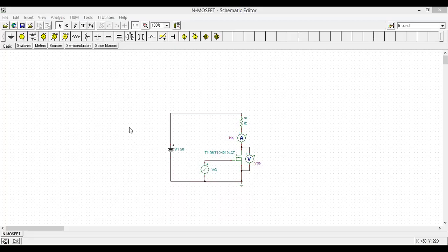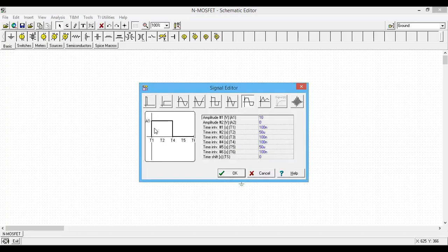All right. So this is the previous table. We had the continuous response and power losses. Now this is a dynamic response. So this is your gate drive signal. I have used it as a square wave. You can see this is the turn on period and this is the turn off period. The turn on period is 50 microseconds and the turn off period is 50 microseconds.